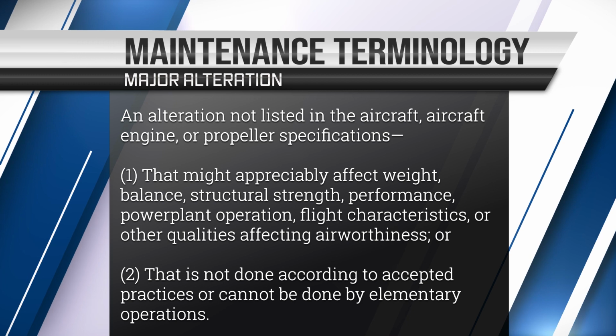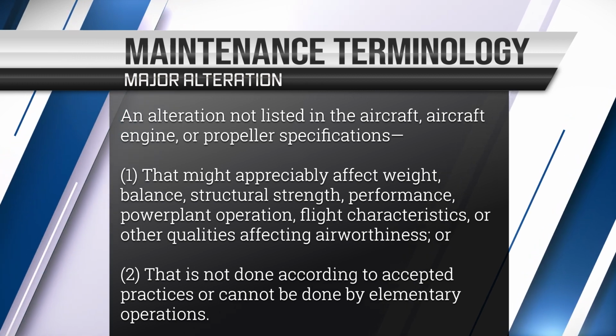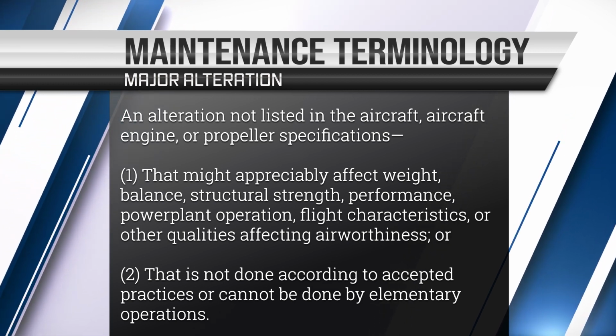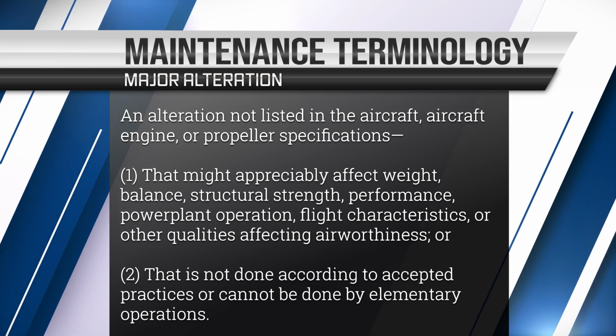Okay, major alteration. What is a major alteration? It means an alteration not listed in the aircraft, engine, or propeller specification that might appreciably affect the weight, balance, structural strength, performance, power plant operation, flight characteristics, or other qualities affecting airworthiness, or that is not done according to accepted practices or cannot be done by elementary operations.